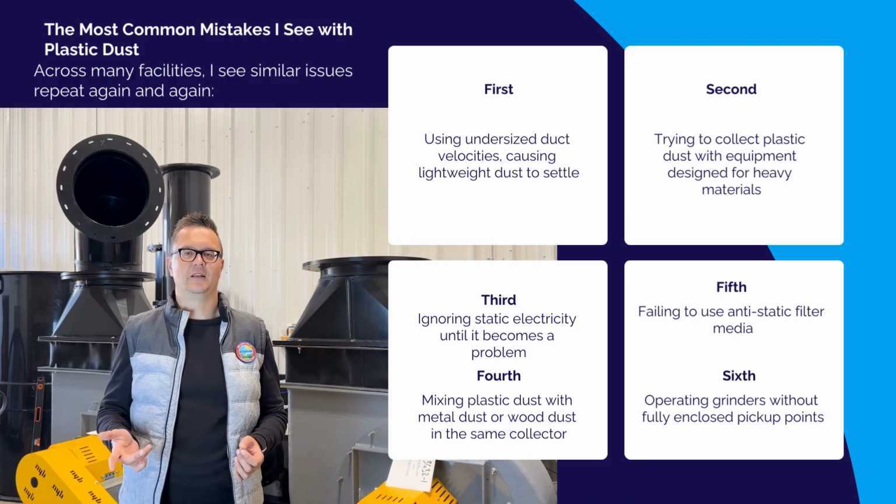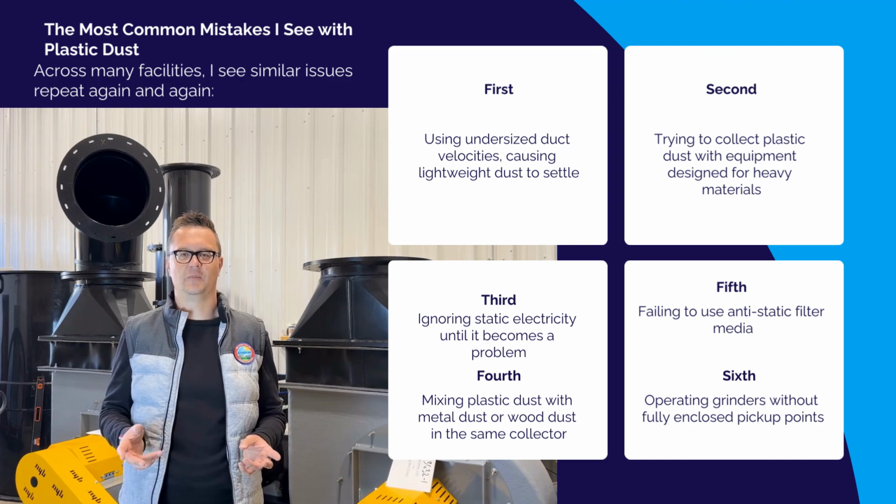Fourth, mixing plastic dust with metal dust or wood dust in the same collector. Fifth, failing to use anti-static filter media. Sixth, operating grinders without fully enclosed pickup points. These mistakes reduce efficiency and increase safety risks.